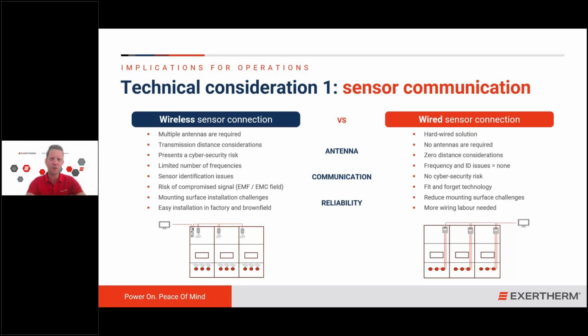So with regards to wireless sensors, typically when you're looking at the pictures at the bottom of the slides here, when there's a transmitter and a receiver, typically there's going to be receiving side antennas required for catching the temperature measured at the measuring spots in the first place. Often there's multiple antennas required, sometimes inside the low voltage compartment, sometimes even located within that same power compartment.